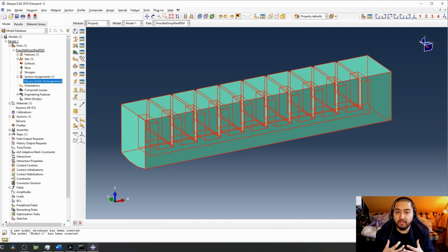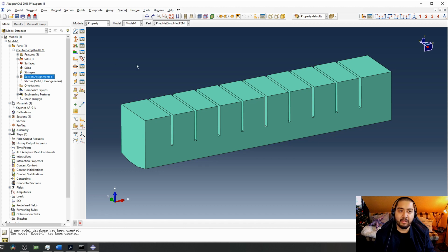And then the next step in order to follow this tutorial is to create surfaces. I would really recommend, for the sake of simplicity and to make an easy life, to define the surfaces that you know you need to work with. For example, which kind of surfaces do we need for this example? We need the inner surfaces, the inner walls.